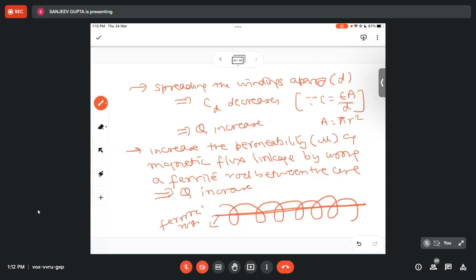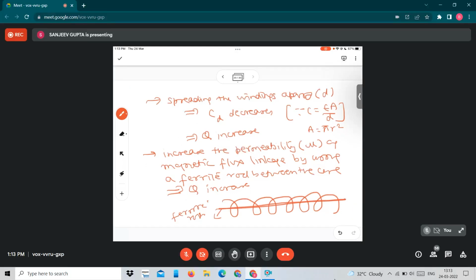So again, just to go over this, my inductor is used in LC filter also, in oscillator also, and sometimes to introduce the delay also, because delay is nothing but phase change, and phase is very important here. We will discuss and continue with that. But basically, what we have learned in RF electronics is that your R, L, C will not behave like a simple R, L, C. They have parasitics associated with them.